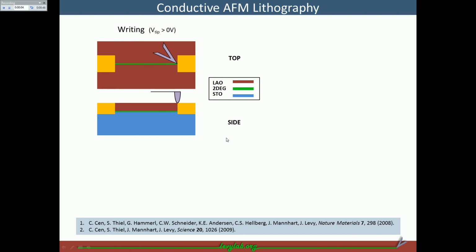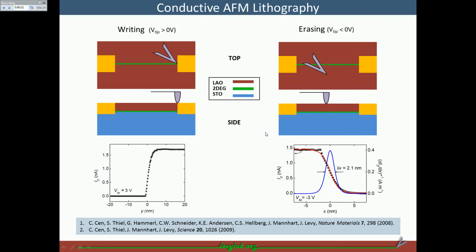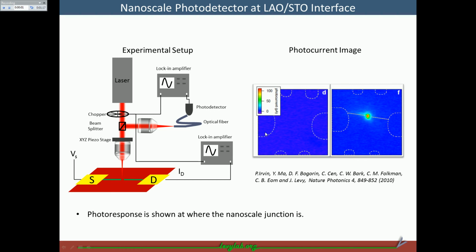So if we use the conductive AFM lithography from one electrode to the other, we will create a nanowire between these two electrodes. And regarding the jump of the superconductance, then we use the negative high voltage on the tip and create the cut in the created nanowire. Then the superconductance will drop to the background. Wait, sorry, just one thing. You keep saying superconductance, so it's conductance. All right, a minor thing.